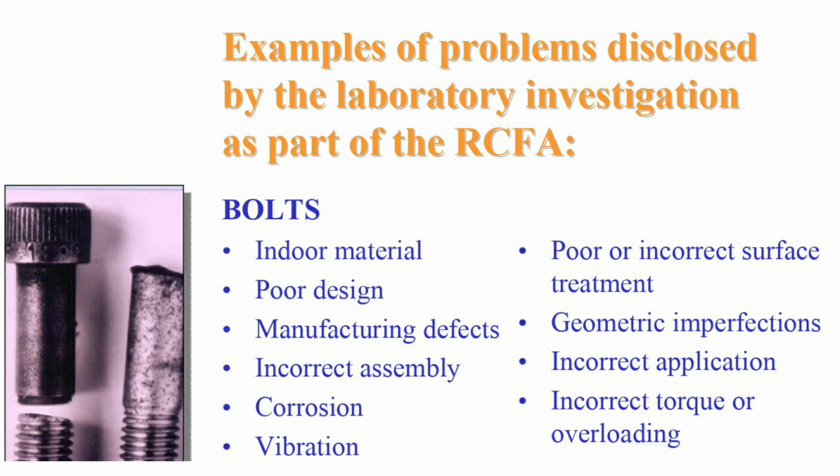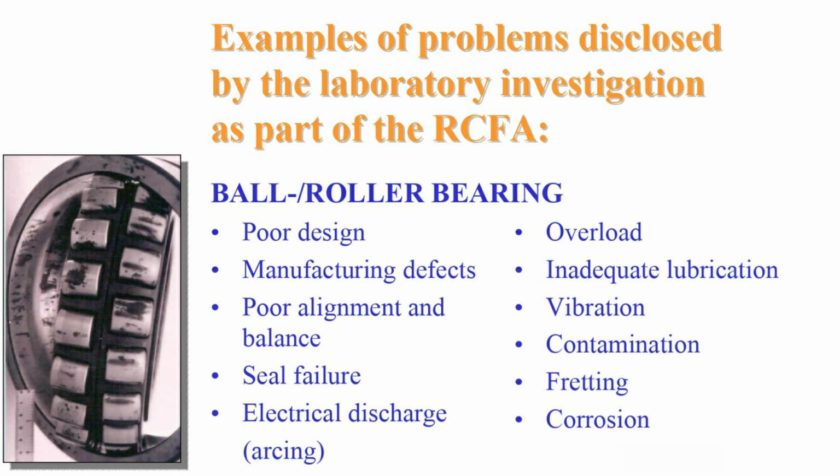Examples of problems disclosed by the laboratory investigation as part of the RCFA: ball and roller bearings. Poor design, manufacturing defects, poor alignment and balance, seal failure, electrical discharge, arcing, overload, inadequate lubrication, vibration, contamination, fretting, corrosion.